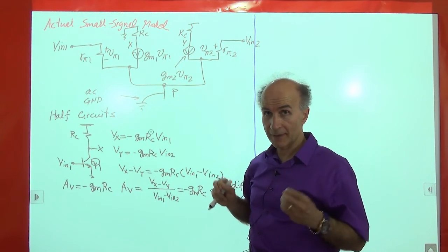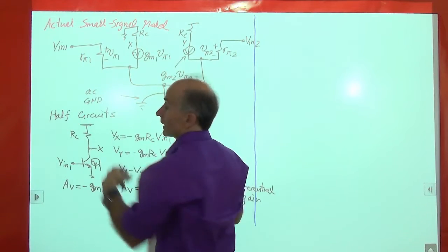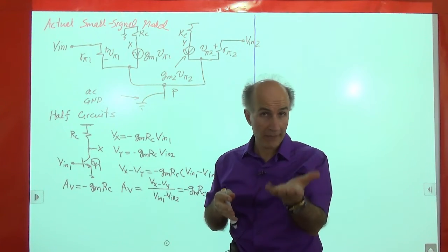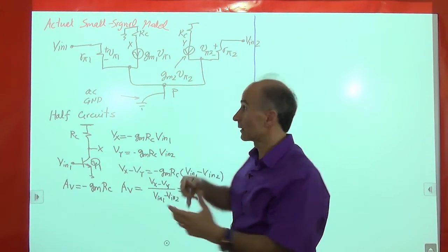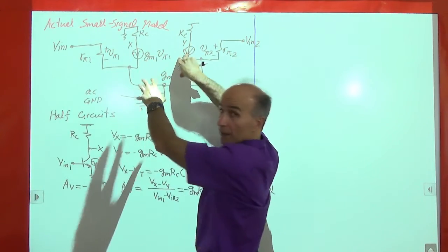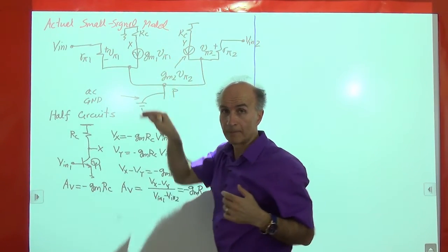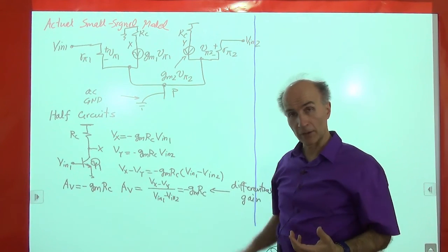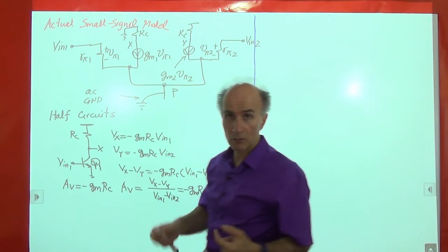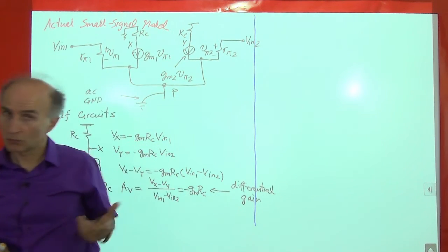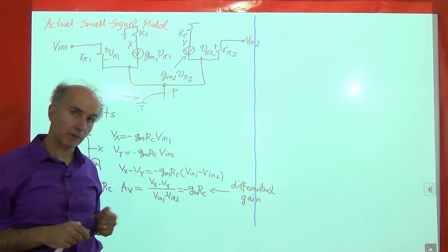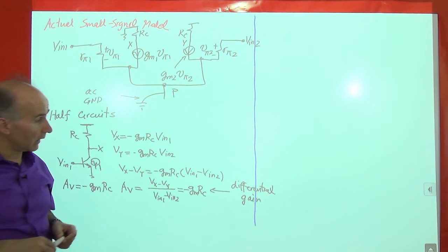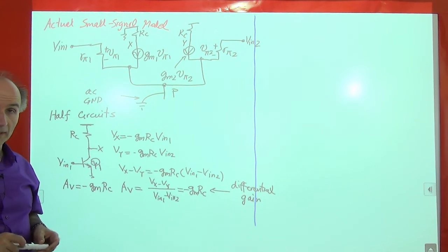So for example, the signal coming to these two is somehow differential. So if it's a single-ended signal from this microphone, it goes through some circuitry, maybe a transformer, as I showed you before, becomes differential, arrives here, is amplified by the circuit, and then it's produced at X and Y. And when we measure Vx minus Vy, we see that we have gain, and the gain is given by this much. So if that gain is reasonable, then it's a reasonable amplifier, right? So indeed, the differential pair can act as an amplifier from this perspective also. Okay, that is the small signal analysis of the circuit.